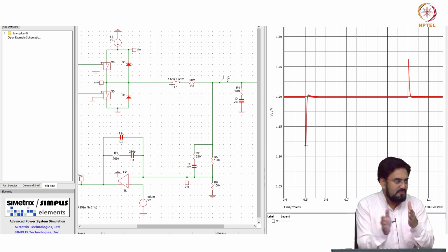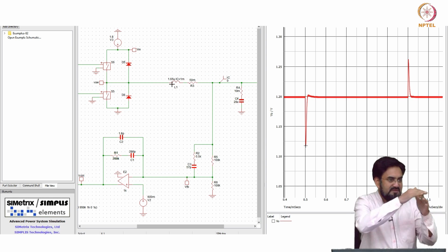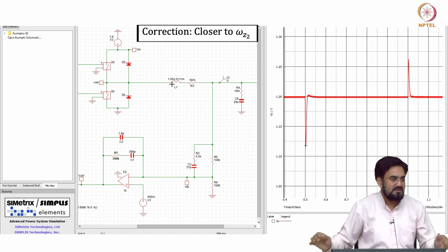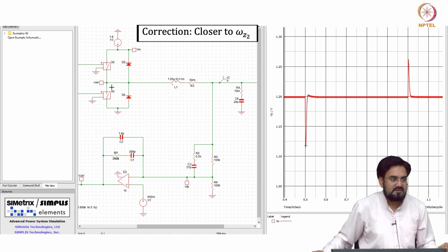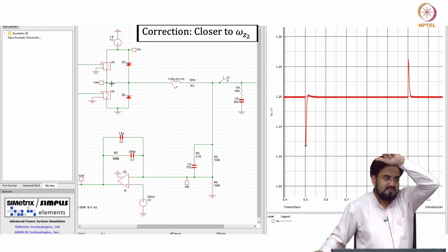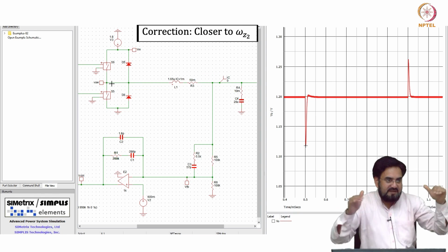The curve means your omega z is shifted lower, so it will be flatter for a wider frequency range. Okay. So what you have is an integrator, then the first 0 will make it flat, then the second 0 will raise the gain. In between is the flat region.